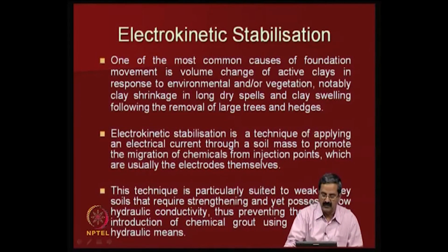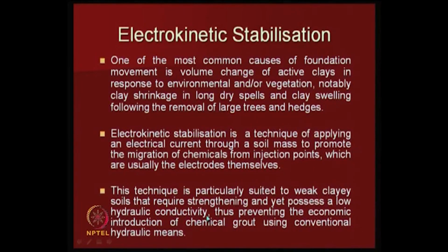Actually, it is very useful for weak clay soils that require dewatering and yet possess a low hydraulic conductivity. So the permeability is very low. For example, if I want to do consolidation, it takes a lot of time. Even preloading and all that work to some extent, or even the technique we discussed, vertical drains. In fact, you may not believe, vertical drains have been combined with this technique to accelerate the process further.